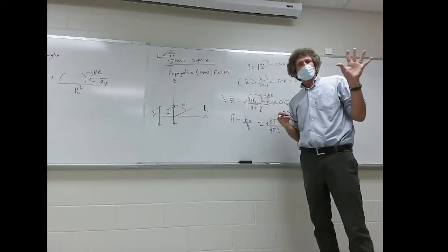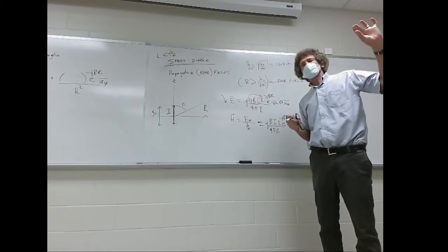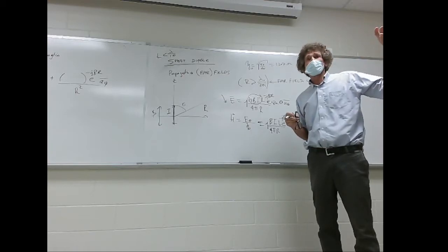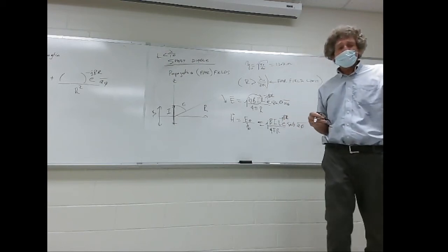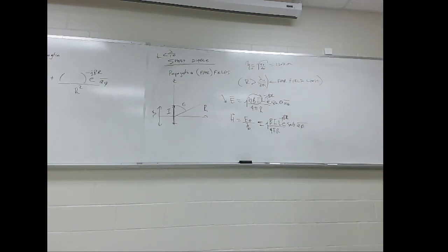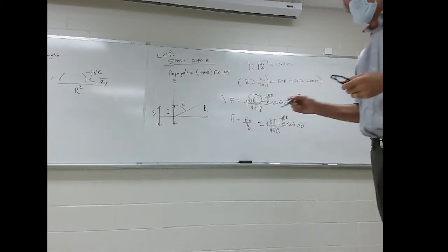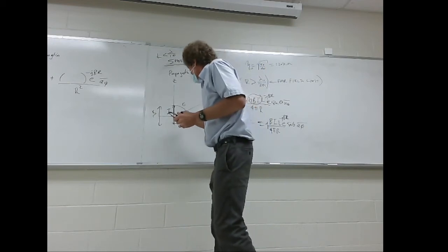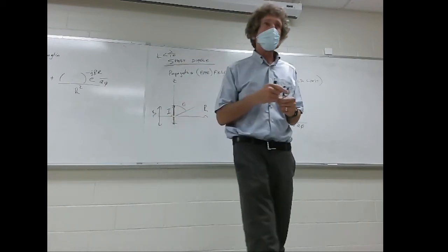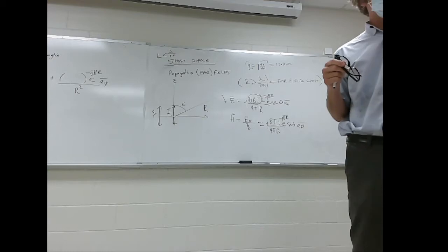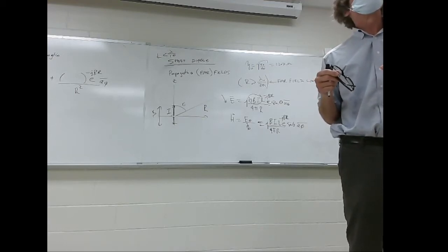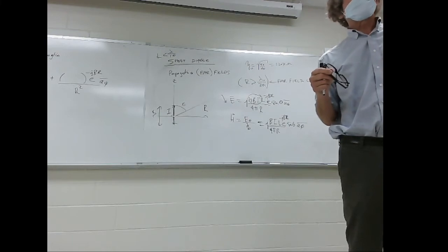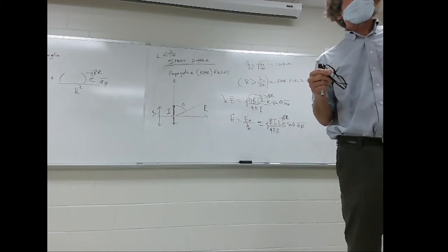Let me just make you appreciate this. So I got a short piece of wire. I know it's a lot shorter than the actual wavelength, right? The wire is much shorter than the wavelength. So let me give you a concrete example. Suppose I'm at 300 megahertz. That's the driving frequency. And where it would be driven, I didn't show you, there would be a gap there, and just put plus or minus a voltage that's changing at 300 megahertz. Y'all follow me on this, class? What's the wavelength of 300 megahertz? Well, it's c, 3 times 10 to the 8th over 300 times 10 to the 6th, or 1 meter.